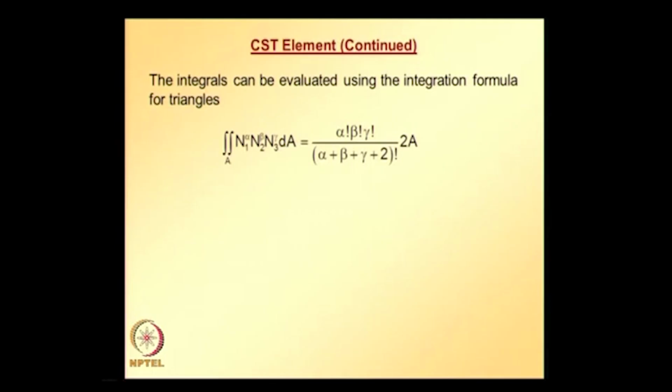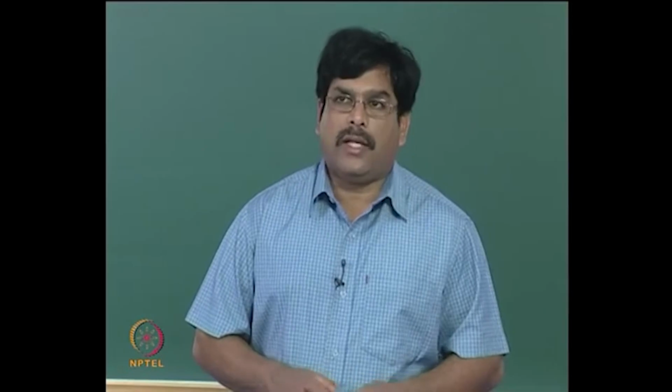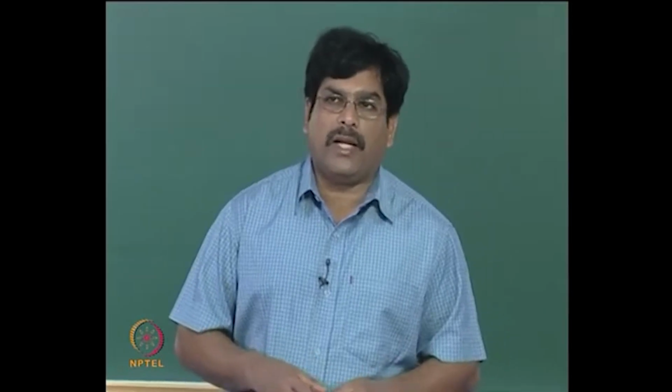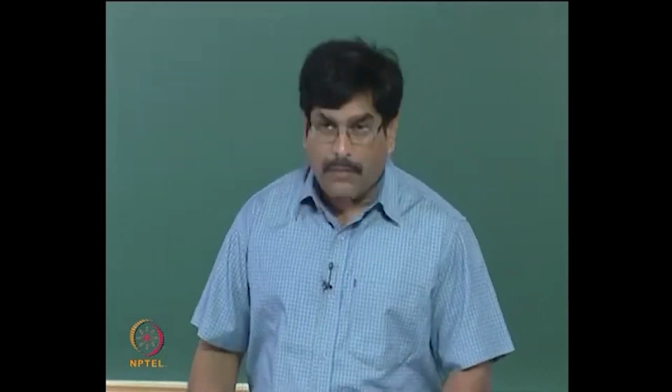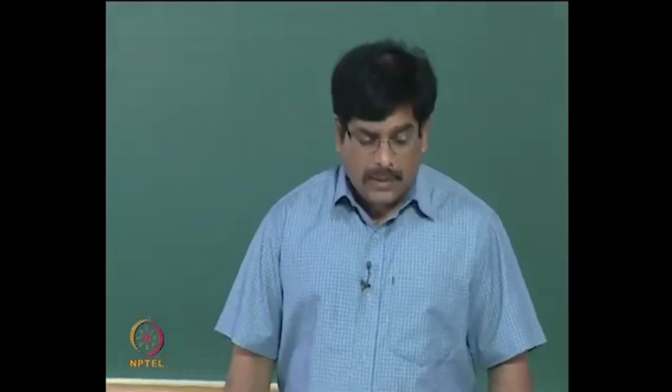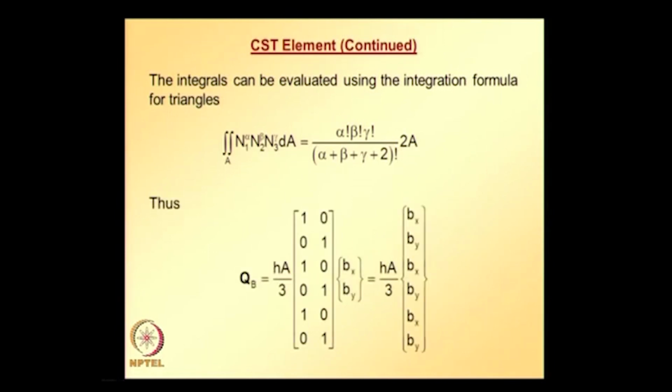Depending on the integrand, if it consists of only shape functions, then we can use this. Otherwise, we need to use numerical integration that we discussed earlier. Adopting either of these, we can get the equivalent nodal vector due to body forces.